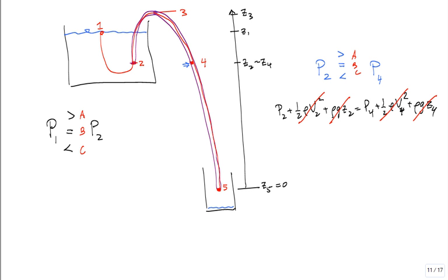A lot of people forget about fluid flow. They just came out of fluid statics. They say, hey, you've got a tank, I see this pressure going down, so the pressure at 2 has to be higher. That's what they'll say. But things are moving. Things are happening from 1 to 2. Talk about the kinetic energy at 1. Negligible. What about the kinetic energy of a little pack of fluid at 2? It's whipping along.